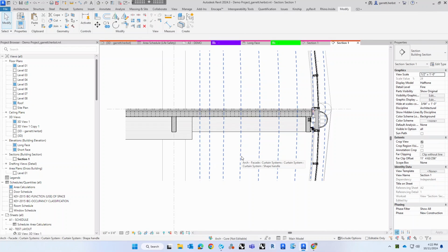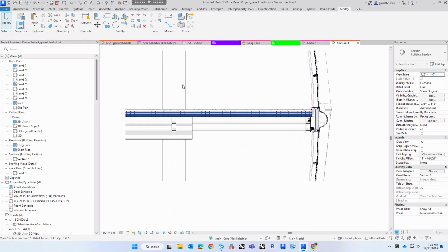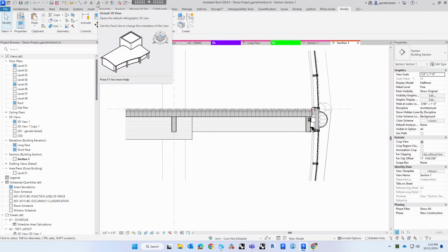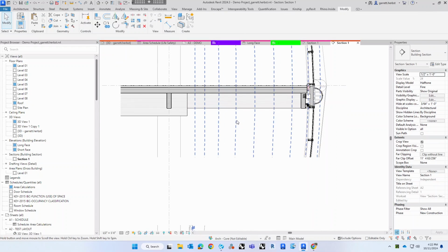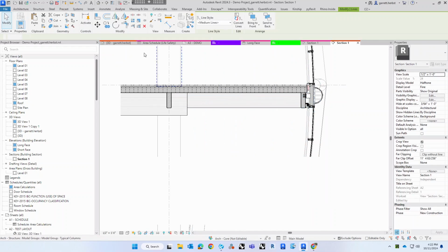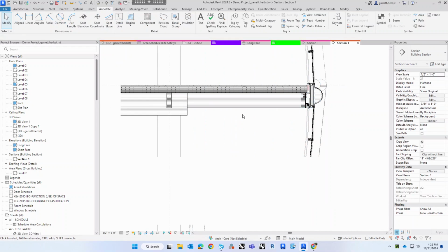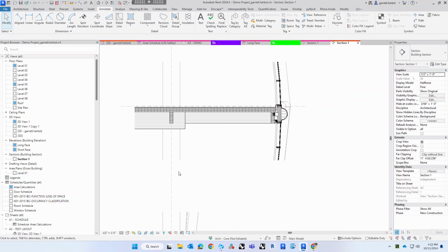Can you cantilever it and then support a curtain wall system from it? Probably not. It all depends. You could oversize your CLT, you could oversize your purlins. If you really wanted to, you could put a diagonal brace between the perimeter and the column and brace it that way.